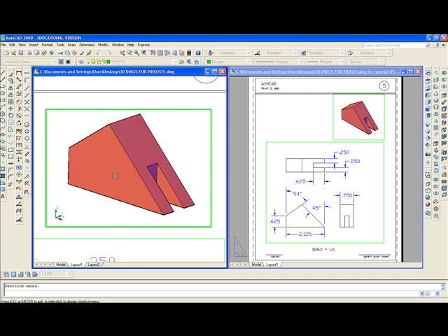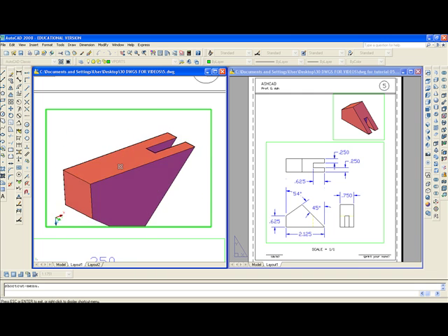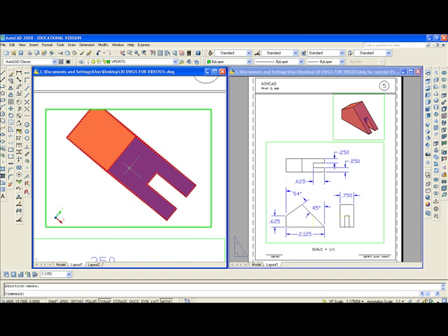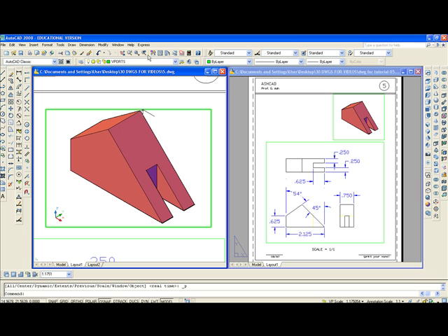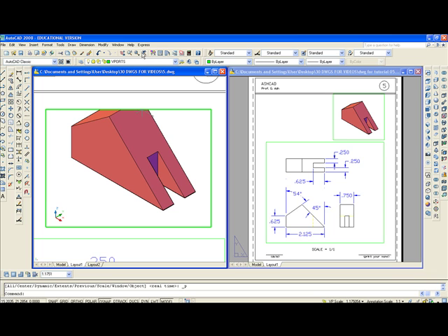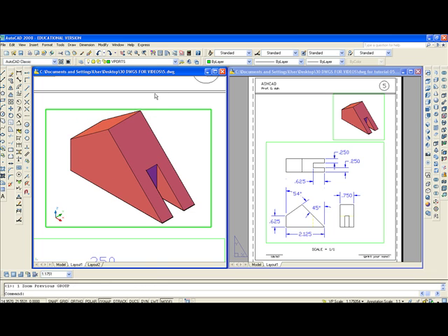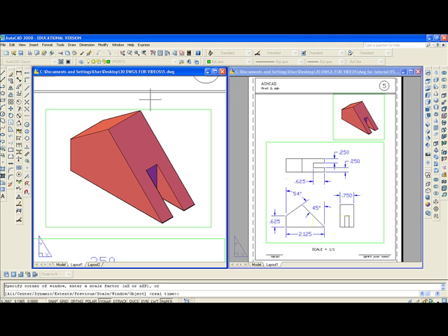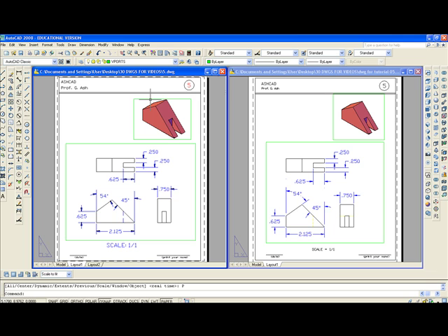Everything about the drawing looks okay, so I'll right click and exit, and I'll zoom previous. Then I'll zoom previous again. Now I'll redo that, I'll undo that. I'll double click outside viewport. Now I can zoom previous, C enter, P enter, either way.